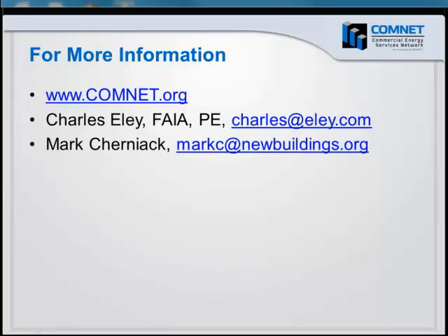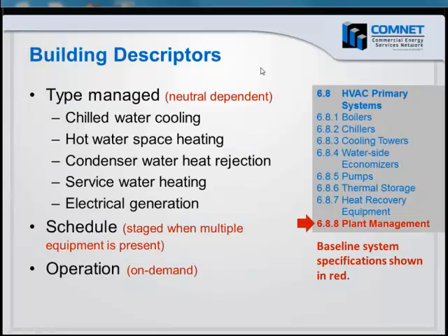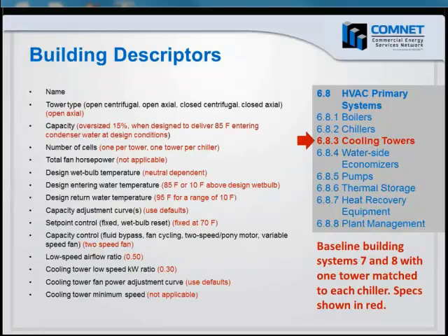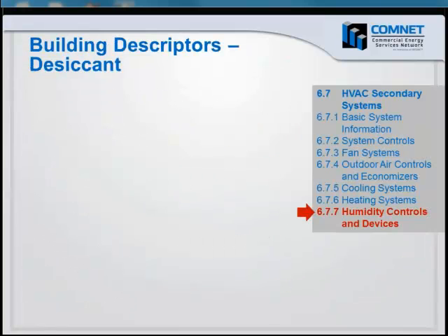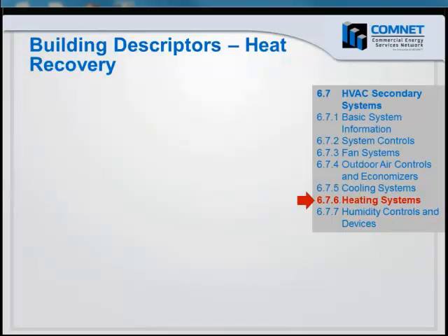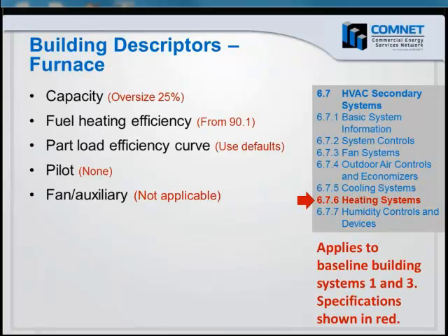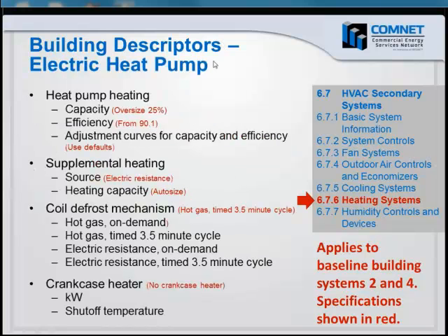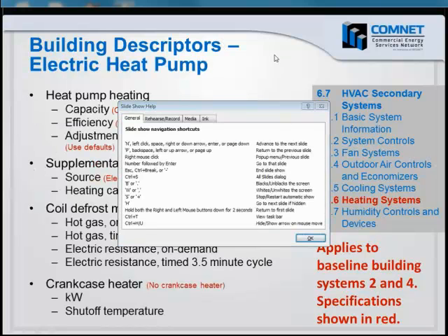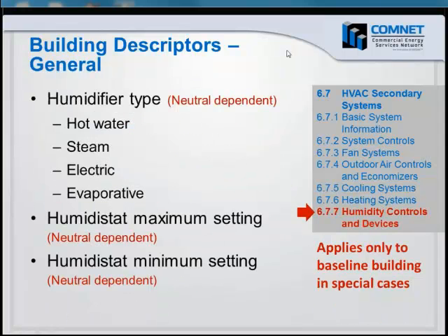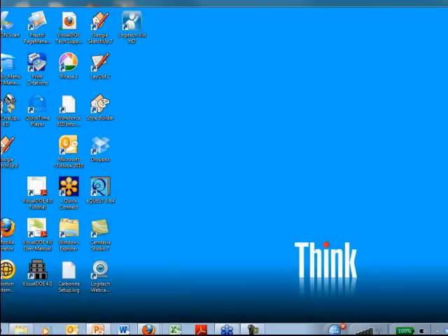Thanks. I had a couple of questions. Could you go back to the slide on the heat pump efficiency? Okay. The question is about the baseline efficiency. I think you're looking for a calculation that uses the fan brake horsepower, and this is a big issue where we don't know what the fan brake horsepower is for the baseline system. Different manufacturers have different ways of meeting HSPF or EER or any of these other descriptors, and the fan can use different amounts of energy. So I think you need to develop some sort of a calculation for the assumption of what that fan power is.